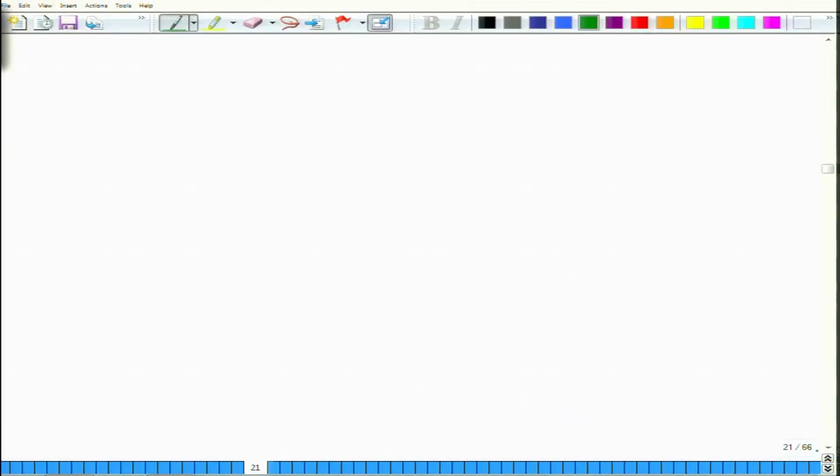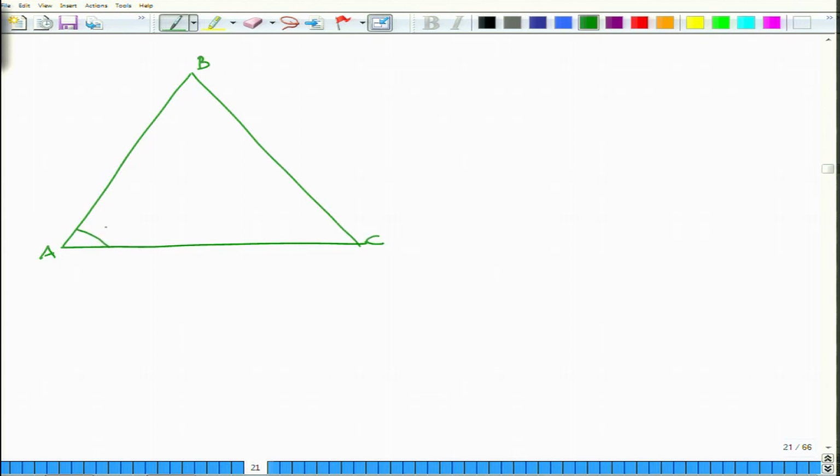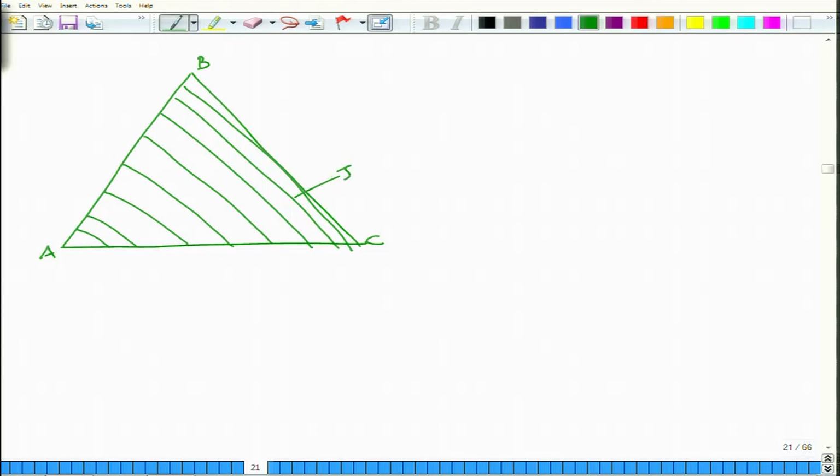So, for example, before I do that, let me just draw the Liquidus plot. For example, Liquidus we have seen, how will it look like? If you draw the Liquidus for such a system, so this is, let us say, A, B and C. The Liquidus may vary something like this. You will have these isothermal contours depicting Liquidus. So, this is basically a Liquidus projection.